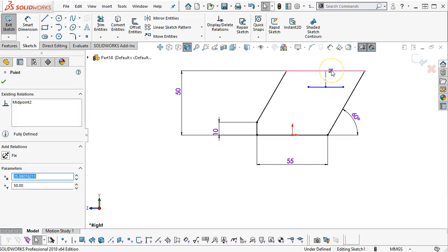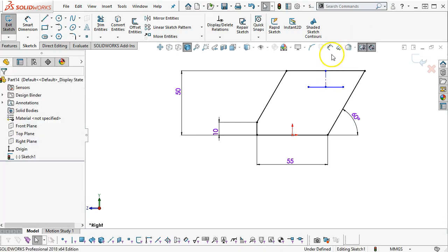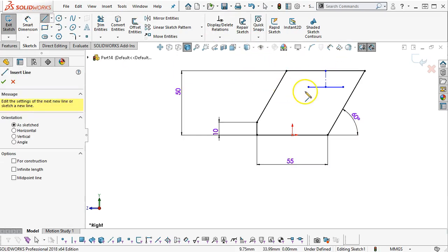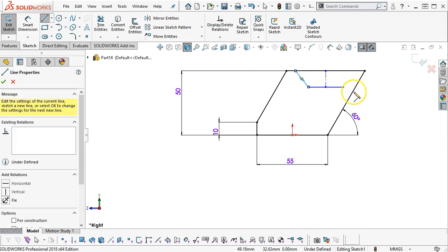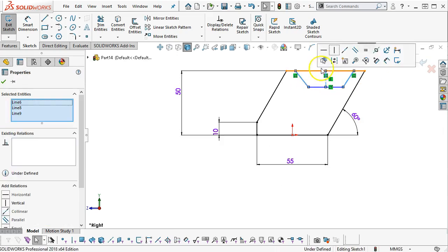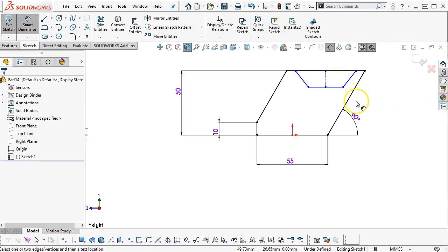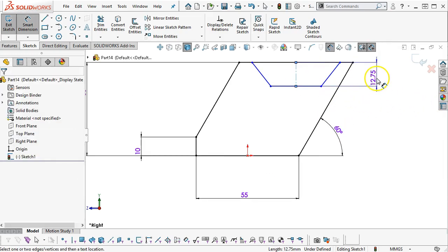We'll switch that from midpoint, so I'm highlighting, identifying the little box, and we're going to go from midpoint to coincident. All right, so the angle coming up, well, yeah, let's go ahead and make those symmetric. All right, we'll get some dimensions in there. So depth-wise is 7 millimeters.